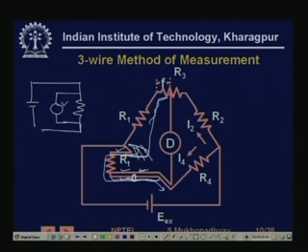These wires are long, but they are the current carrying wires. These other wires are also long, but they do not carry current because this is a voltmeter, a high impedance device. Therefore you sense the potential across the resistive element only and not on the leads. So if you have a 4-wire RTD, you can use this circuit. This is the 4-wire method.